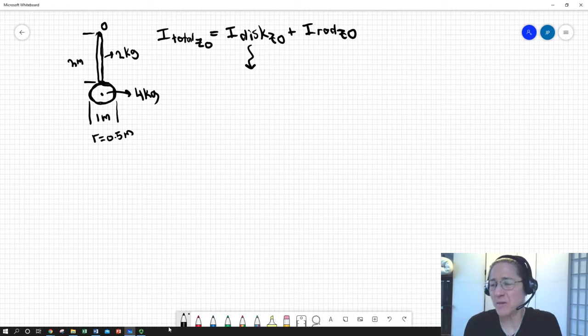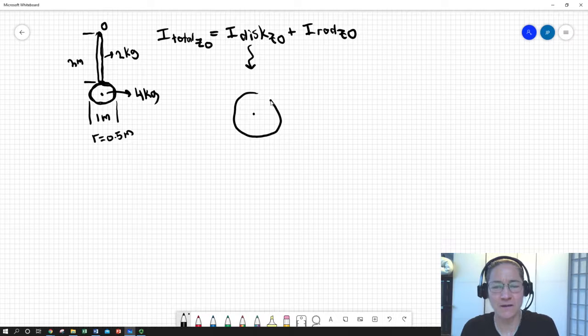And let's assume maybe we didn't have our handbook with us, and we're like, doggone it, I can't remember what the mass moment of inertia is of a disk of some kind of plate about its center of mass. So we're going to assume we've got uniform density, and so the center of mass is at the volumetric center. This is an area problem. We're assuming we have some kind of uniform thickness going in the z direction, so mass for uniform density is effectively equivalent to area. So it's kind of an area-based moment of inertia. Mass moment of inertia is area moment of inertia here.